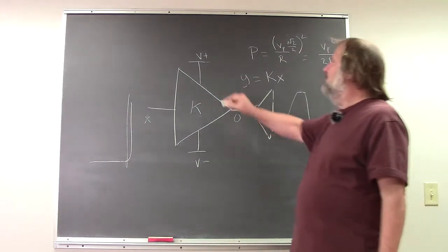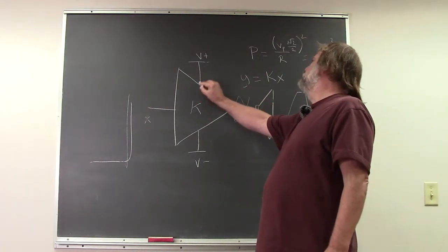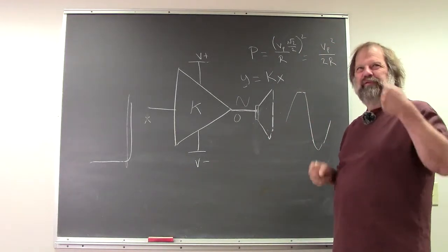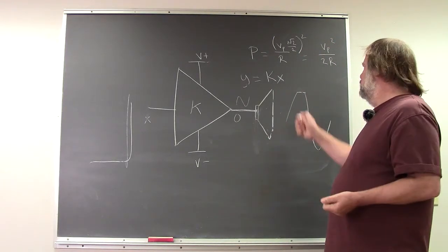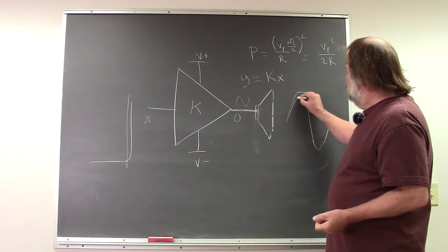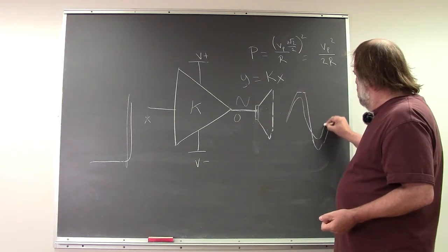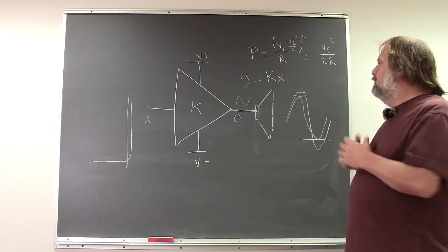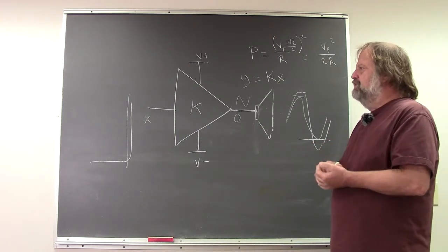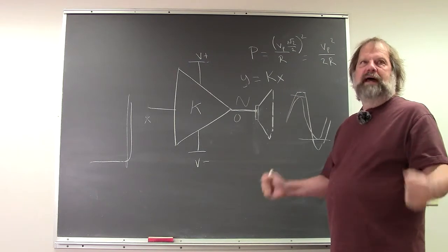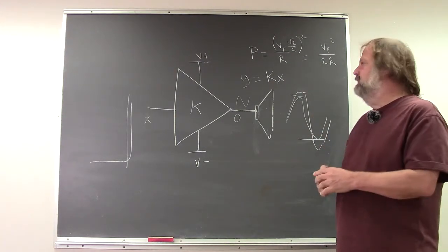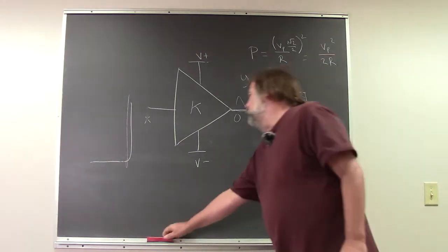And in a practical sense, as amplifiers get close to their clipping point, they usually get a little bit nastier too. So we don't want to be right at clipping, but we'd like to be operating somewhere. If that amplifier clips, we'd be much happier if it was constrained to some region like this. So clipping is not a subtle distortion, it's horrendously bad distortion. All amplifiers that clip are bad in that context. So what does this mean?